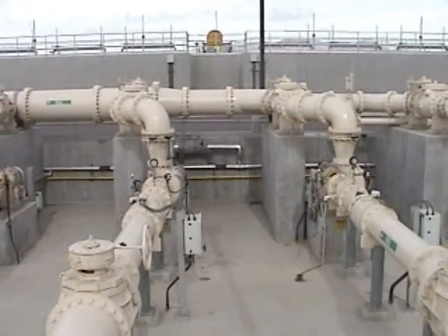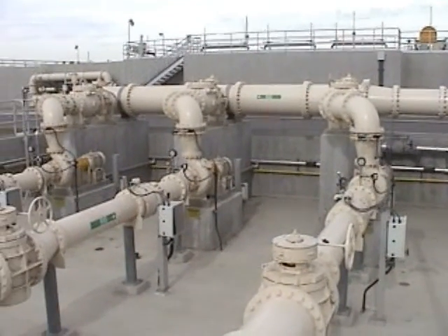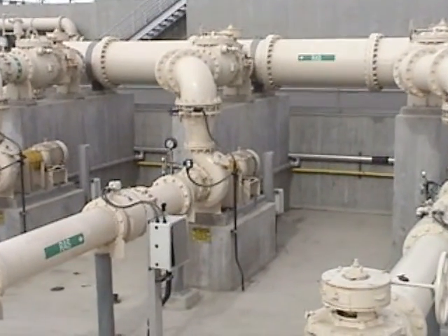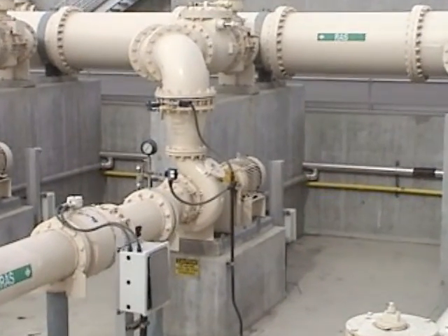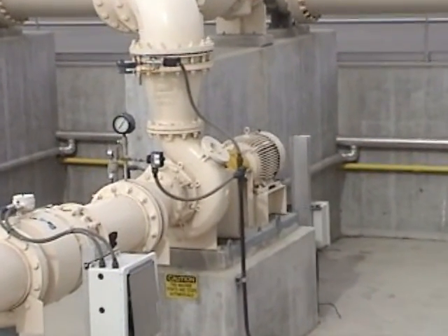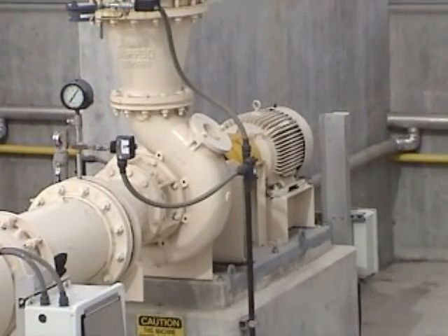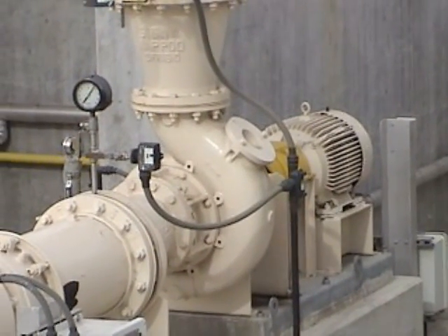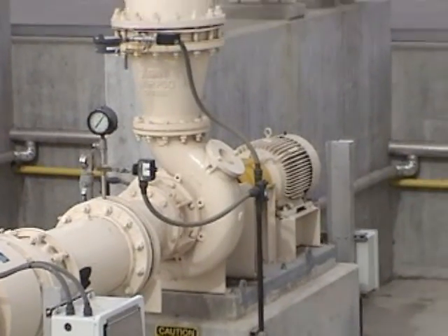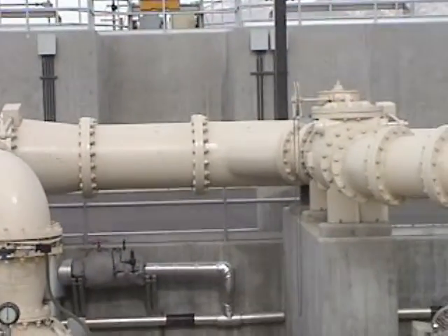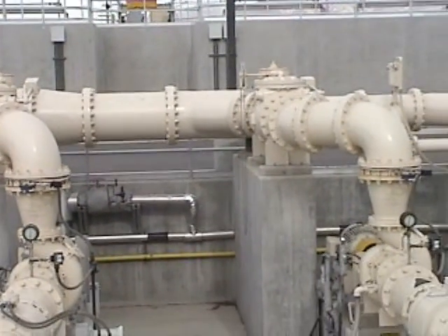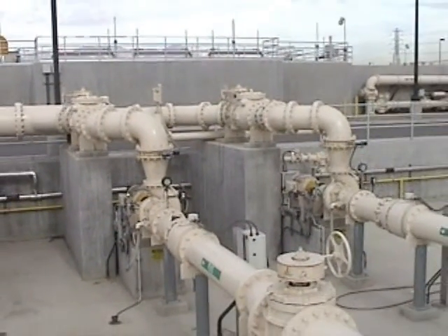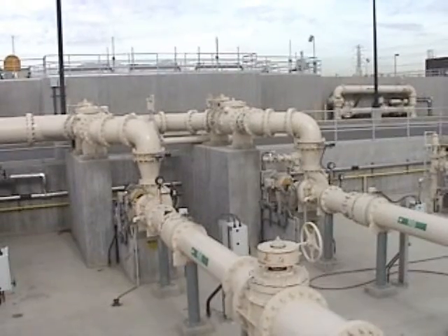These pumps can be controlled from the SCADA system. You can dial in flow rates through the SCADA, or locally you can go into Power Center 2 over there, put them in manual local, and control them with a little potentiometer on the cabinet of the VFD to adjust the flow. They pull the flow from all the clarifiers that we have online through that header, that pipe in the back of the system up about ground level there, and then it pumps it back into trains 3 and 4. It's a single pipe that goes over there, and then it branches off to the 2 trains.